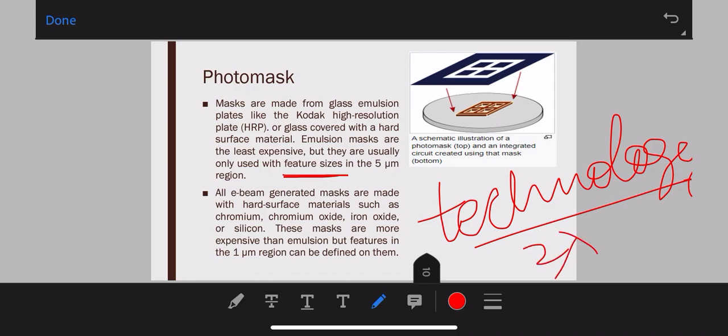So that is the minimum feature size, the minimum size of any source, drain or gate that you can build, the minimum size of a channel that should be there. That is actually your feature size. It means anything should not be less than your technology size. Any structure or design that you are building on your substrate should not be less than your feature size. That is the smallest size.